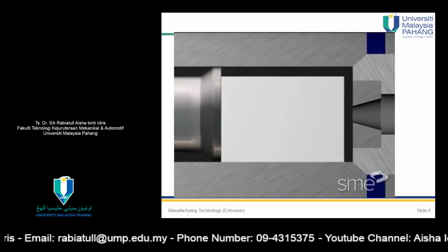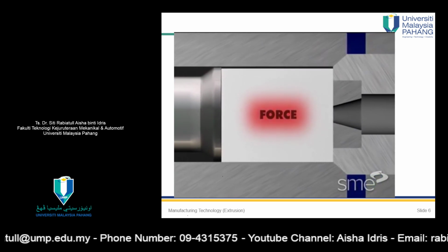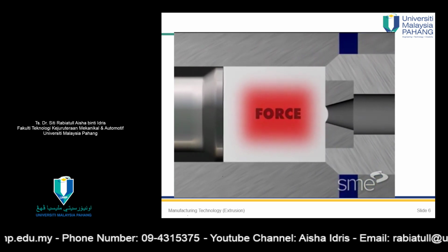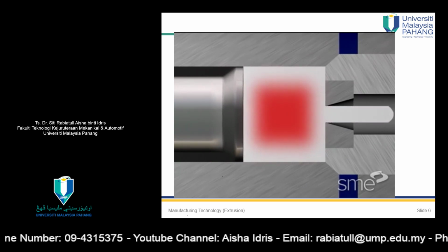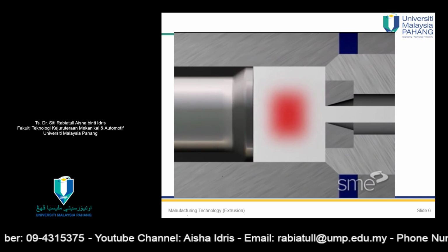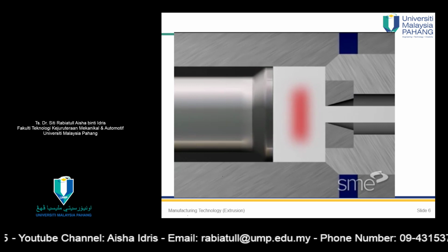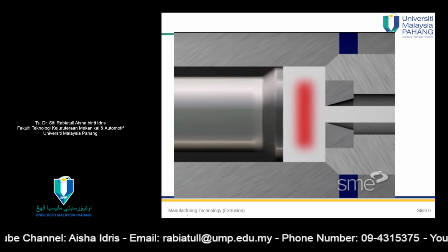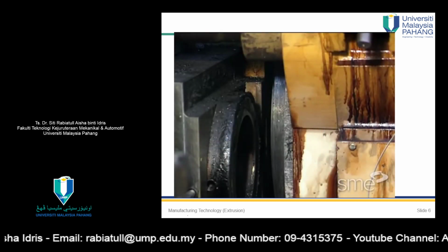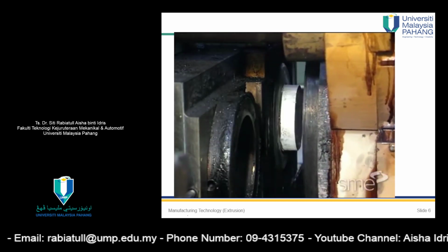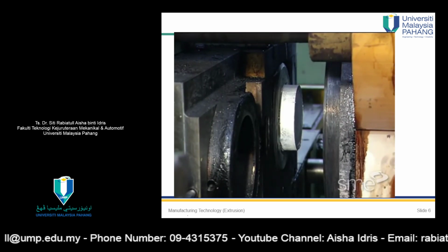Force increases rapidly as the billet is upset to fill the container, then increases further as breakthrough force before extrusion begins. Upon breakthrough, the force declines as billet length decreases until a minimum force is reached. As the billet thins, the force rapidly rises again to continue metal flow radially toward the die opening. Resistance to deformation, or force requirements, increases markedly as the thickness of the butt, or unused billet portion, decreases.